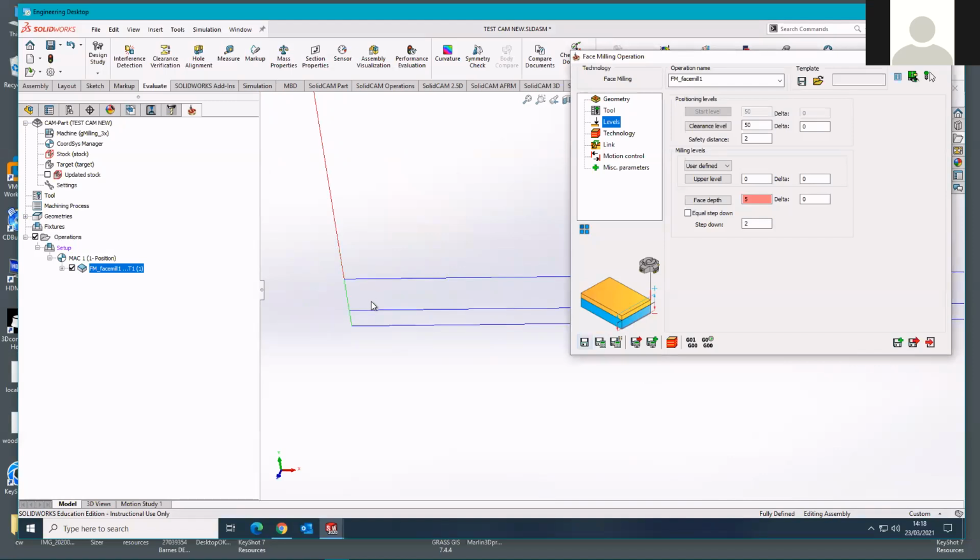The reason I'm sounding confused there is, given that we're cutting 5mm of material away, and I've allowed this tool to cut a maximum of 2mm, I would have expected it to drop to 2, do a cut. It is doing. So yeah, this is the first cut level, and this is 2mm below the top of the stock material and below the coordinate system.